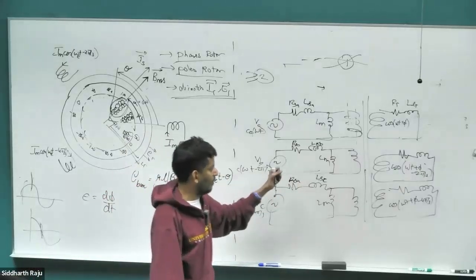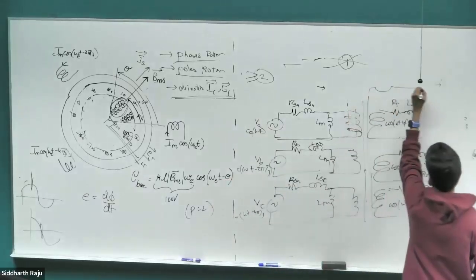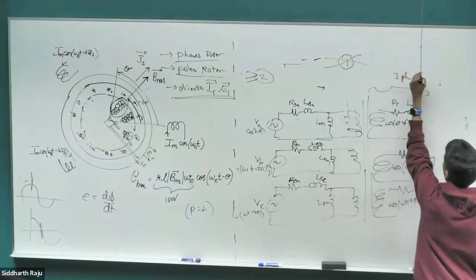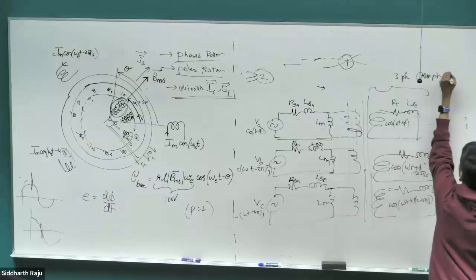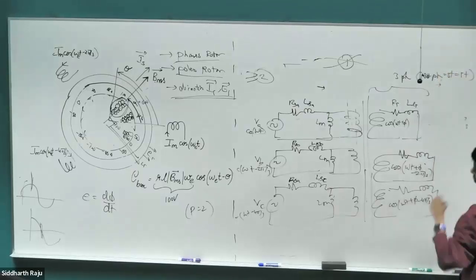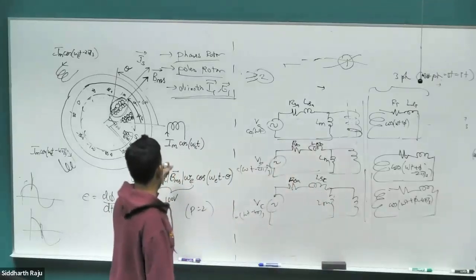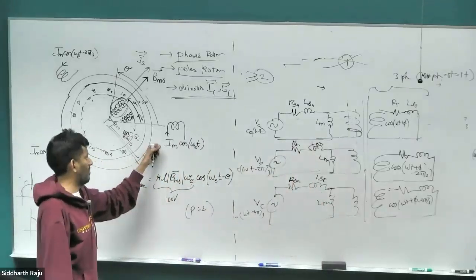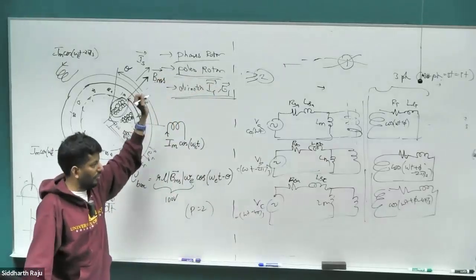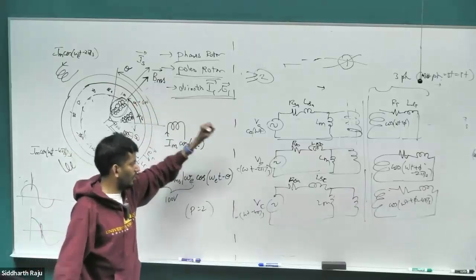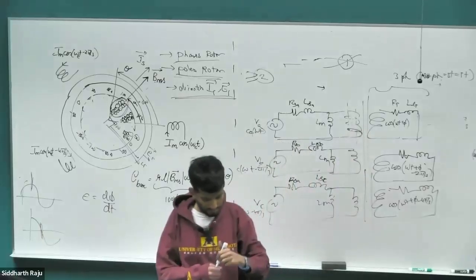Alright, so just to make our equivalent steady state circuit easy to analyze, we are going to model the rotor as well as a three-phase system. Right? The same number of phases on the stator as the number of phases on the rotor. This is only a modeling requirement, not a mathematical requirement. It's not a physical requirement. But the number of poles being the same, that's a definite physical requirement. Alright, because of the pattern that's established in the diagram. The number of phases, that is totally up to you. If you take it in this form, it makes your life much, much simpler.